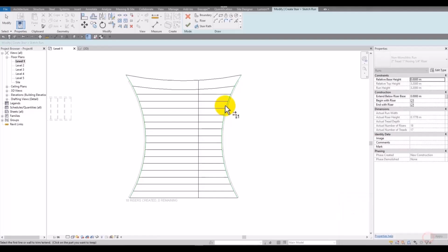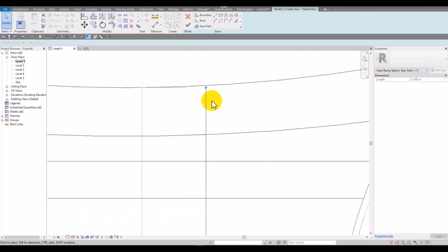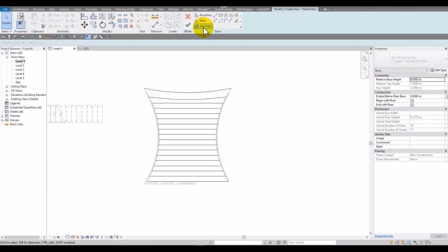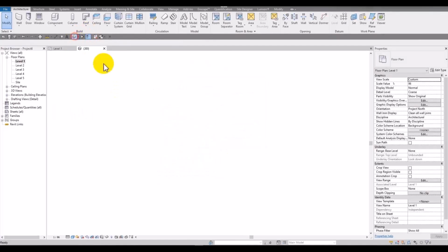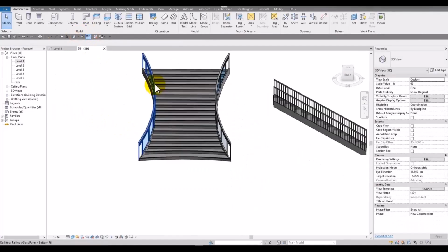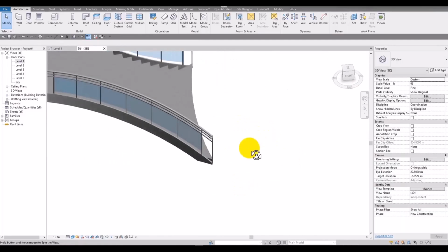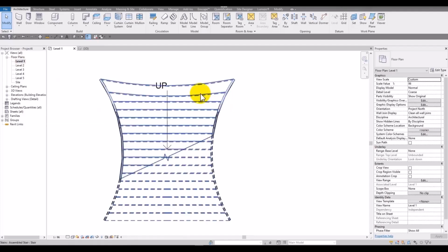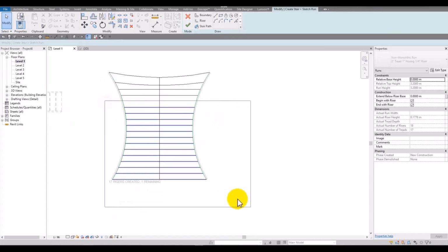Okay, this error is because of the stair path. This line of the path should cover the whole path of the stairs. Here you need to consider the path of the stairs clearly. Start from a point and end. Right now it's okay. And we can have these stairs like this. As you can see, this line is not straight like before, it has a curve. And many shapes and lines are possible, and you can have them for your stairs.